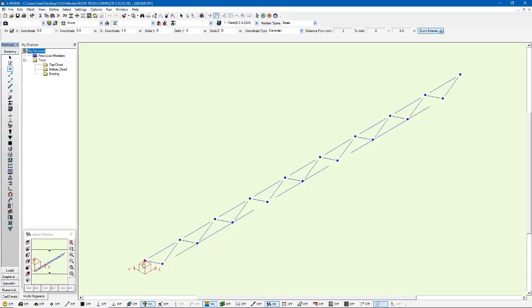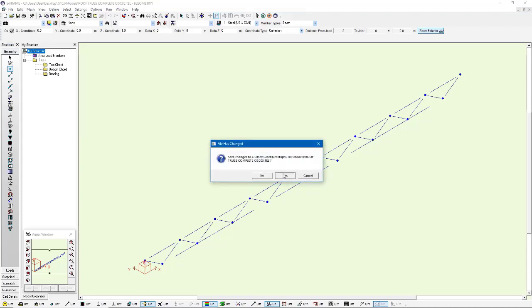And that's going to come in handy because I want to be able to match the two coordinate system origins in my models that I'm merging in order to make sure that I don't have to move things once I get them into the same file. So knowing that this coordinate system origin is 1 meter below the level of the top chord where it's going to be resting on top of my columns will definitely come in handy. So let me go back into that other model for a second.